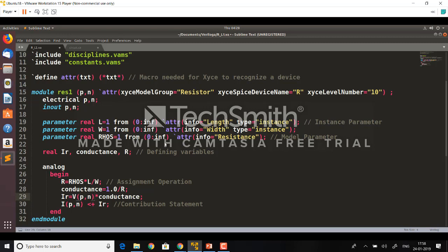If anyone has ever used, I don't know, Mentor Graphics or Cadence, we always use model files, dot mod, from the file, right? If you open a model file, it's nothing but the values of these parameters. Has anyone ever tried opening this? It's a list of constants equal to something, right? It's just that TSMC, for example, what they do is they measure the transistor.